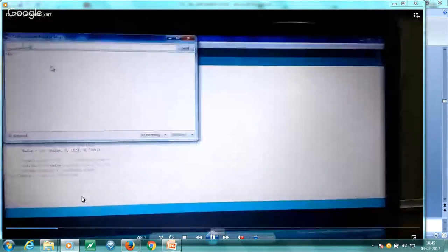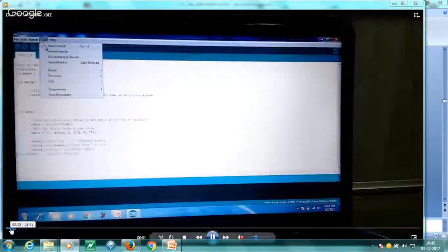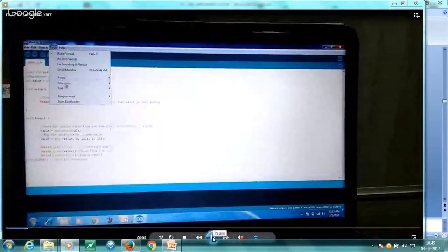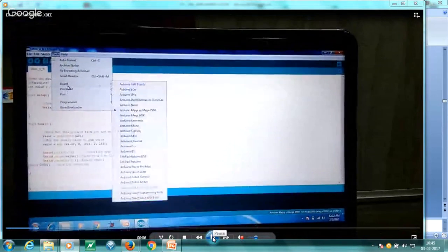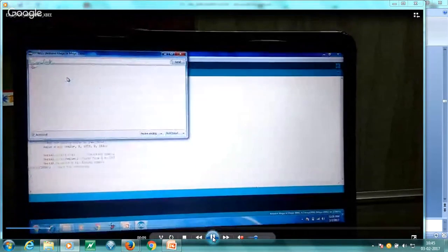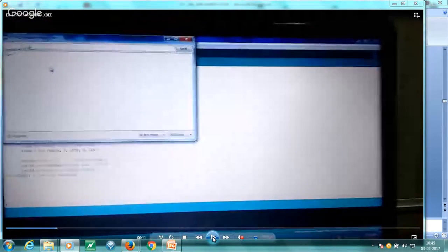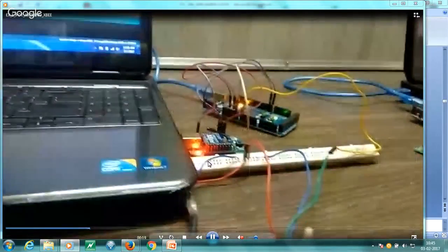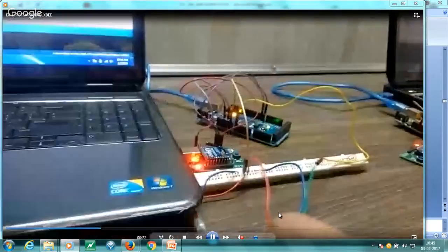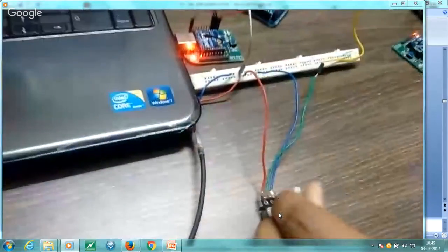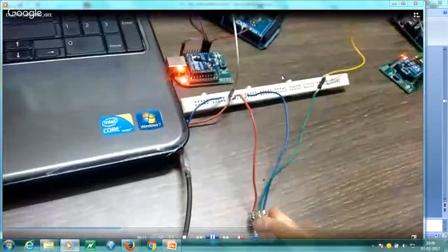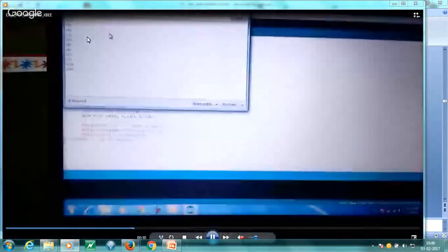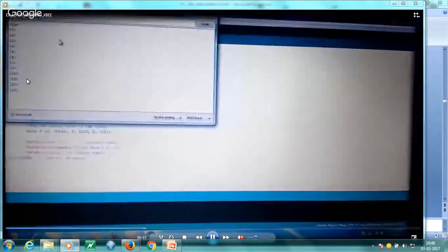And in this video, we can see how we transmit our data. You can see we are going to select our board and port, and the program which is written is your transmitter side program. Here we are getting some value which is input from the potentiometer, like 3, 4, 5. In the setup we can see there are Zigbee modules and a potentiometer, and we change the potentiometer value like this, and there is your Arduino Mega board. You can see the value has been changed like this. So we can get the different values on the serial monitor in the debugging process.